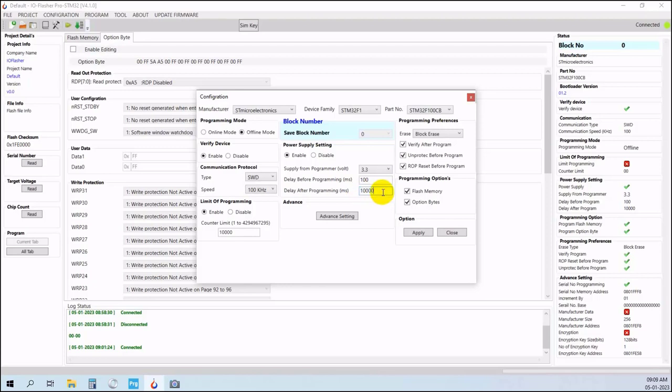So you have to see, it may work in some family, it may not work in some family. Accordingly you have to see which reset is working for you. If power on reset is required, then you have to replug the cable, right? And then you will have 10 seconds or 12 seconds or 15 seconds, whatever settings you do. For that much time, you will have output power coming, right? You do not need to wait till the end of the timing. You can start the programming of a new device also if you have already set this timing on the higher side.